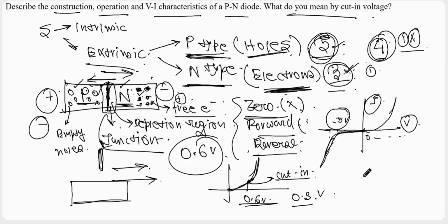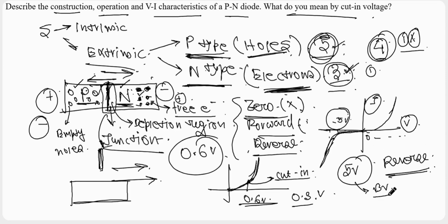So this happens because every single PN junction functions as a Zener diode, and a Zener diode has a breakdown voltage. This particularly occurs when the PN junction is operating in a reverse bias condition. Okay. So during the reverse bias condition, the PN junction acts as a Zener diode. And this 5 volt is the breakdown voltage. I am representing it here as BV.